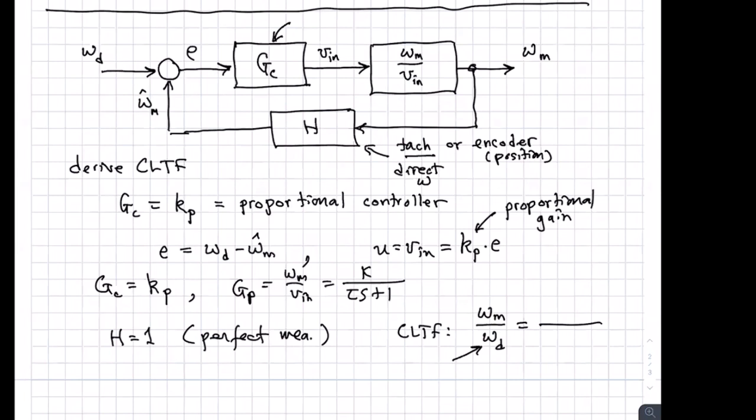I'm hitting on my outline. Pre-lab problem number 1, I'm asking you to describe the derivation of the motor model. I've done that for you, so you should be able to do that. Present it in the form of an open loop transfer function between motor shaft speed and input voltage in symbolic form, which means in parameters, so don't plug in any numbers.